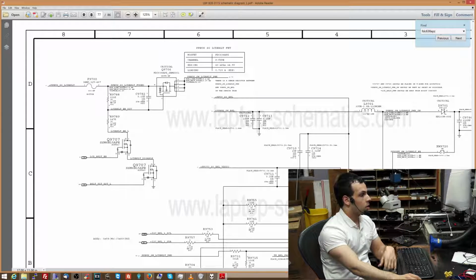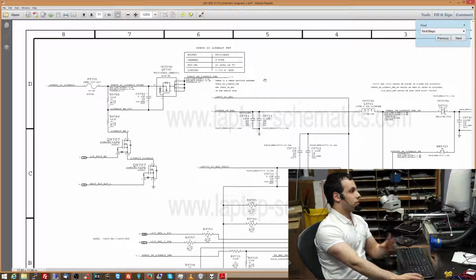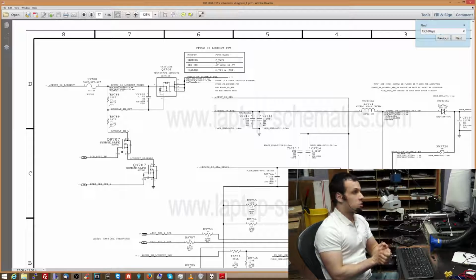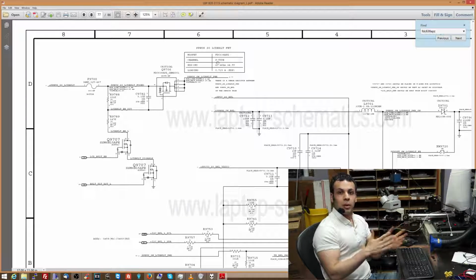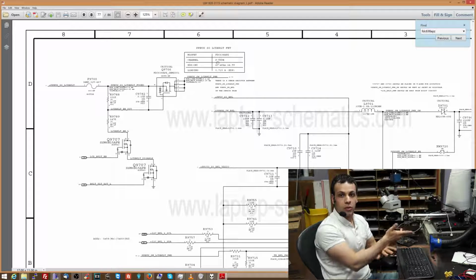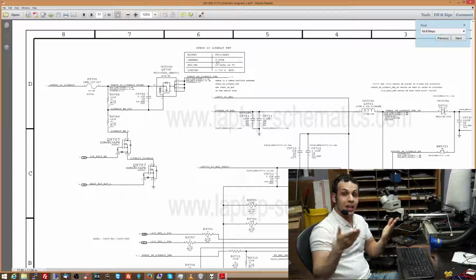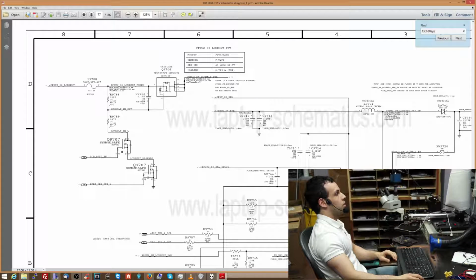So you can use transistors to do a lot of cool things in a circuit. For example, over here, do we want power to go through to the backlight? Well, I don't know. Do we have LCD backlight enable coming in? If LCD backlight enable is present over here, then let's turn this on. Otherwise, let's send this to ground. Now, there are different types of MOSFET. For example, I don't want my backlight to be on when my computer's closed. I don't want my backlight to be on if it's been idling on a desk for 5 or 10 minutes because the battery will die. I want to be able to tell it to turn the backlight on or off. I'd like to be able to have that type of switch. I don't want the backlight to be on anytime there's power flowing to the computer. And this is one of the ways that we do it.